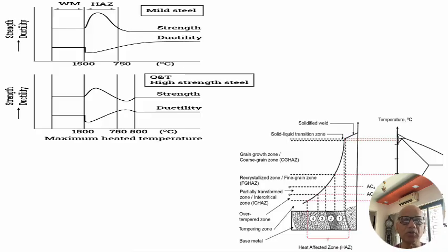But mild steel doesn't give you the strength, the corrosion properties, and the high temperature and low temperature properties. So you select various other alloys and materials, for which you need to really take care of the heat affected zone.